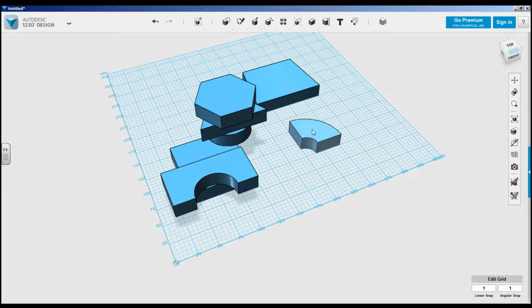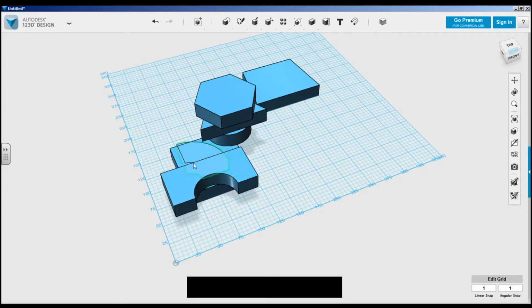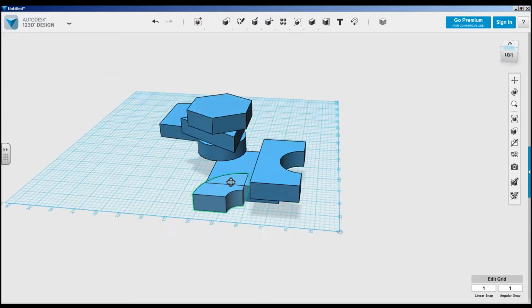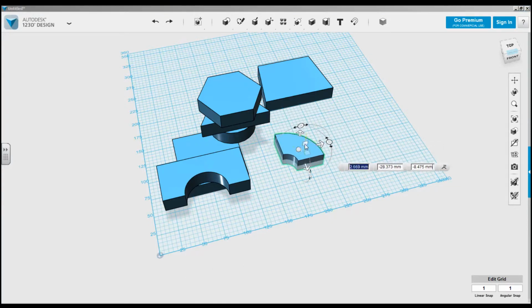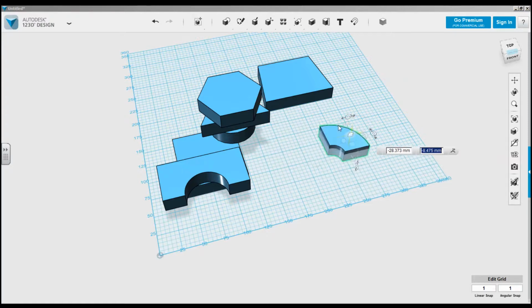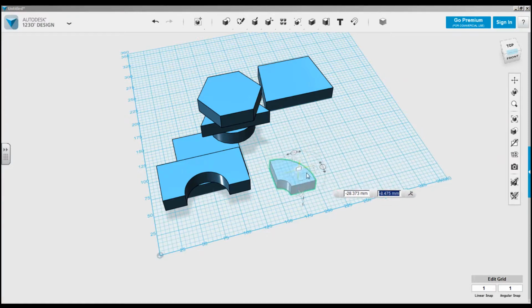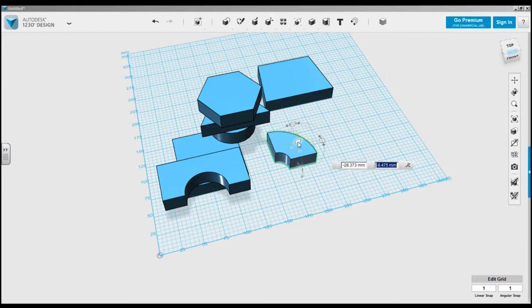and then move them into position with the other tools. It's never a good idea to simply click and drag to place something. You lose all concept of where it actually is, and the same thing will happen when you're moving if you drag from there or use one of these discs here, because they do lock 2 of the planes but not all of them.